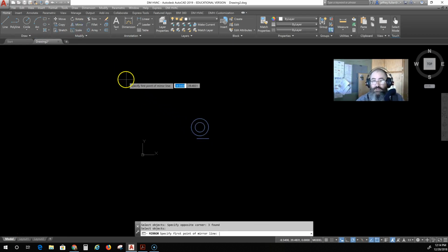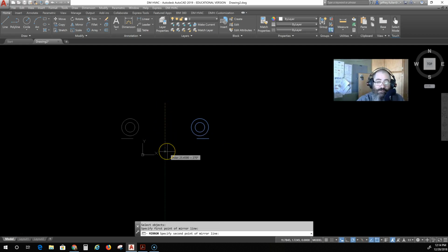Once I draw the mirror line and I click to establish that as the definite mirror line, it has a message in the dynamic input. It says erase source objects. If you just click enter, or if you just click again on the mouse, it will erase them. As you see, the box below it has No selected. So I have to click on the enter button to get it to accept that answer. So no. And there we have our two objects.